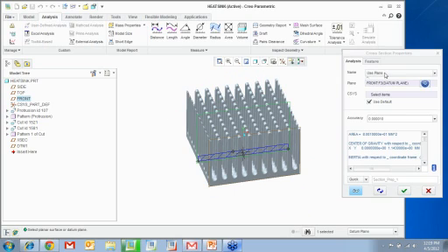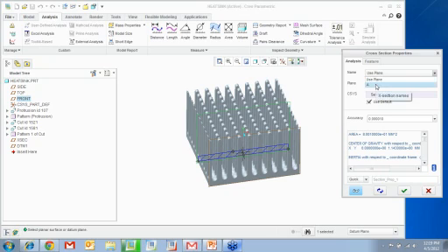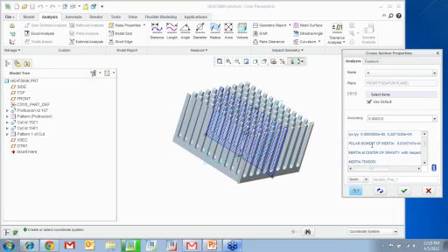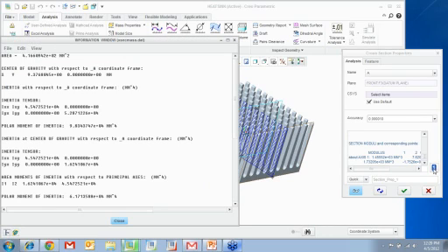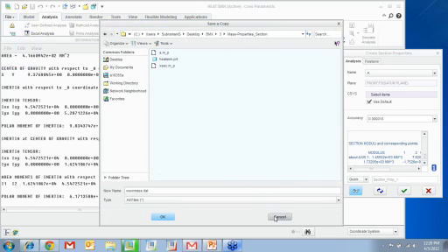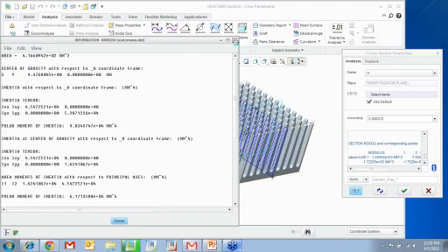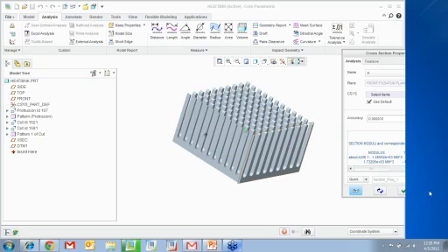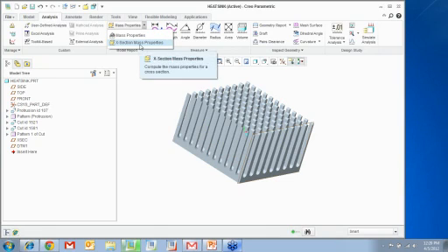and you can choose different planes, or you can also use the drop down and pick your cross section. So that's my cross section, and it tells me the area, center of gravity, moment of inertia, all those details right here. I can click on this eye, it comes out here, and I can also save it as a DAT file. So you have your cross section mass properties that you can look through. All you have to do is dig here and find that.